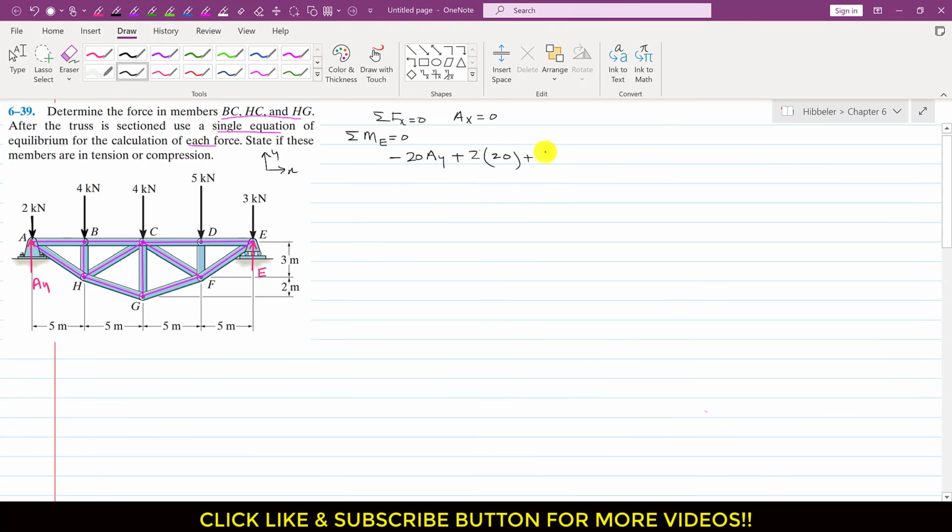So I will multiply this with 15, that is 4 into 15. This other 4 kilonewton force is also producing a counterclockwise moment, so I will write plus 4, and the perpendicular distance is 10 meters, multiplied by 10. Similarly, this 5 kilonewton force is again producing a counterclockwise moment, so I will write plus 5, and the perpendicular distance is 5 meters, so I will multiply this with 5. And this 3 kilonewton force and this EY, both of these forces are passing through point E, so they will not produce a moment about point E, since the moment arm of both of these forces is 0, right? So this will be equal to 0.